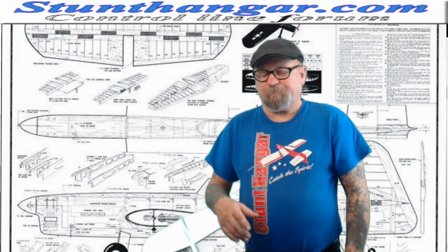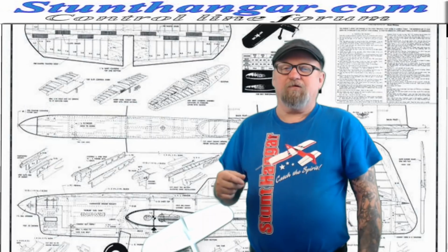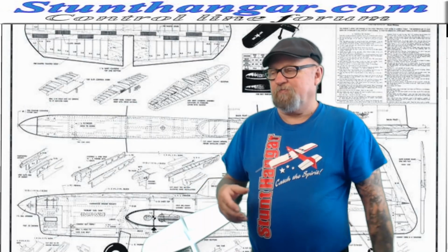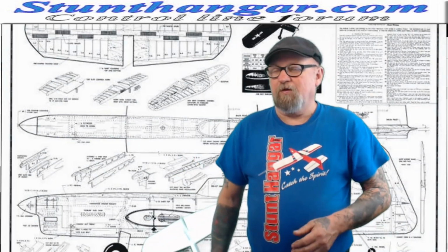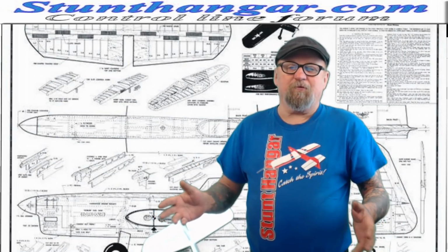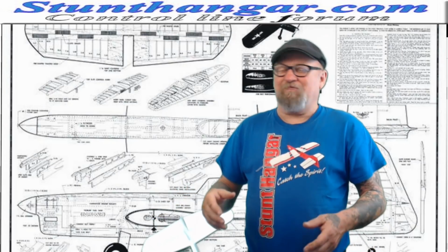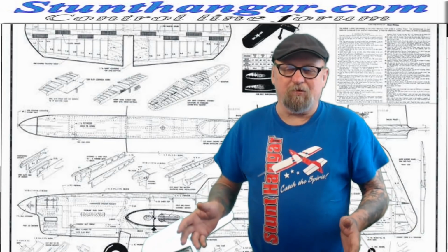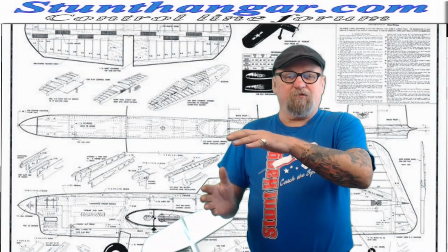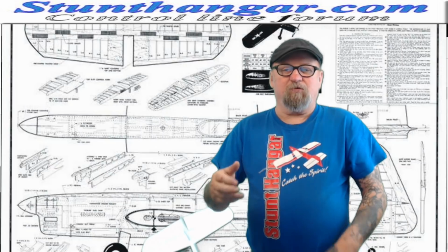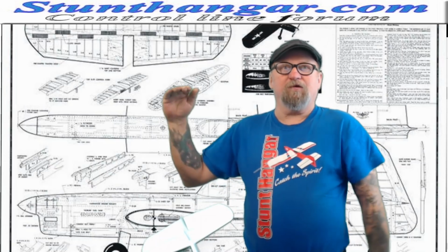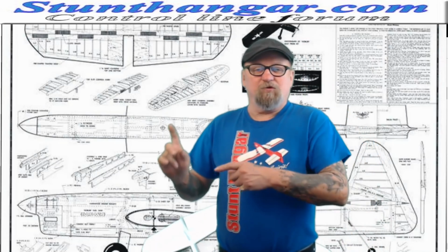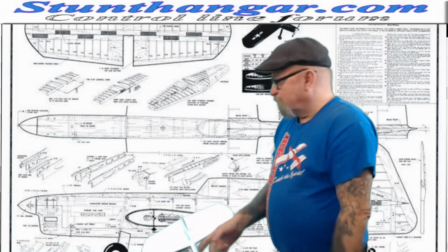So now let's talk about flap size. A lot of guys like big flaps. Well, you have to have big flaps if your airplane weighs a lot. If it doesn't weigh a lot, you don't need much flap. As a matter of fact, it's a detriment, because the more flap you put into a light airplane, the more it acts as an air brake. So the airplane actually stops in midair and then goes around the corner. So in my opinion, you want to fly off the tail.